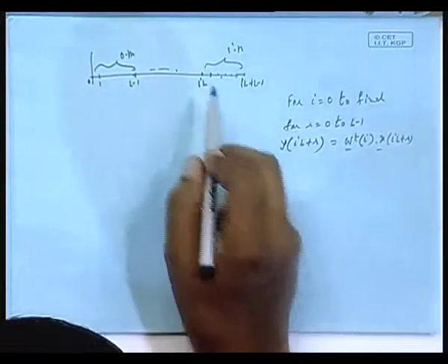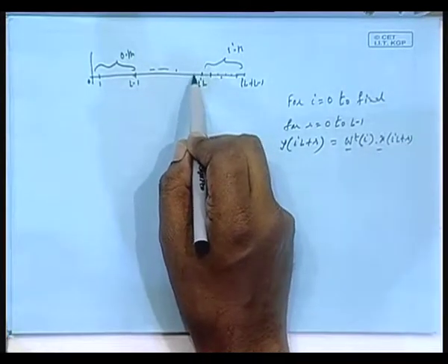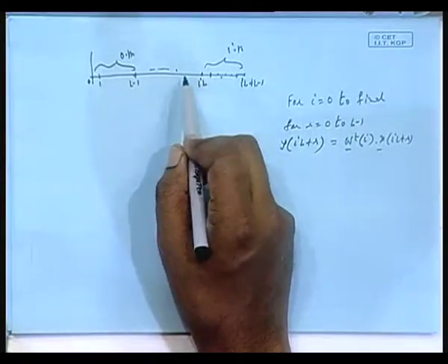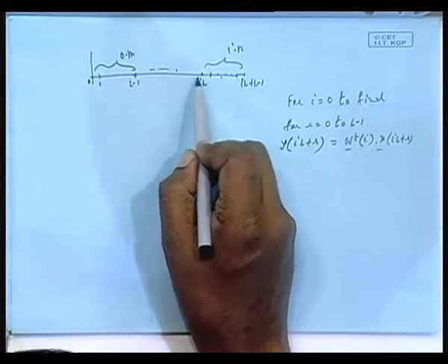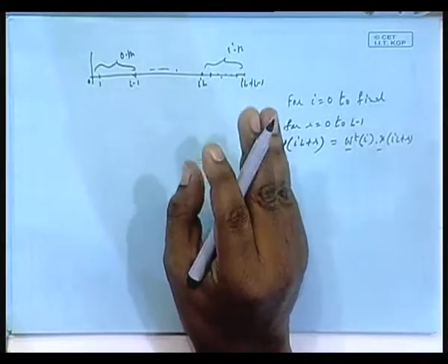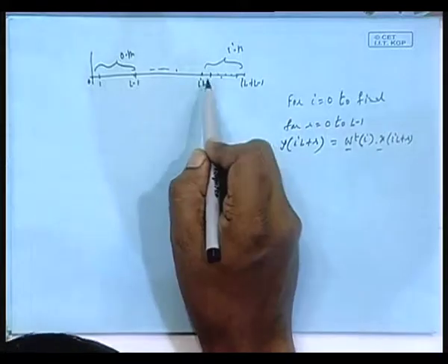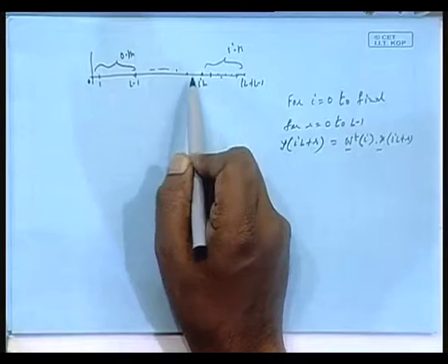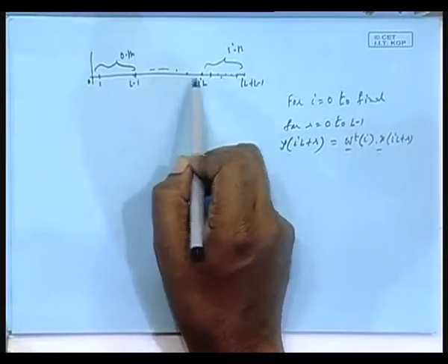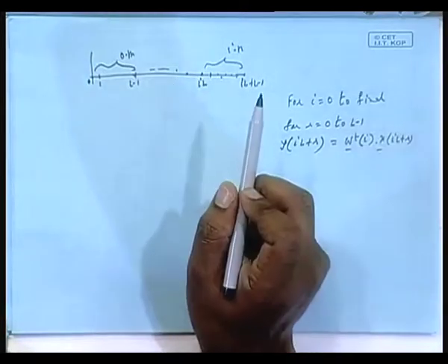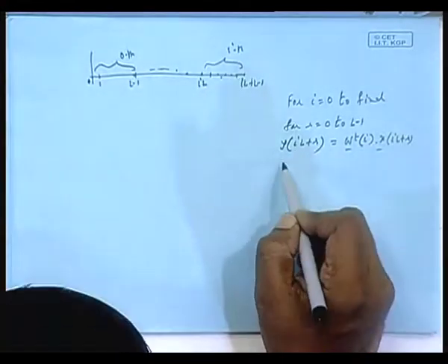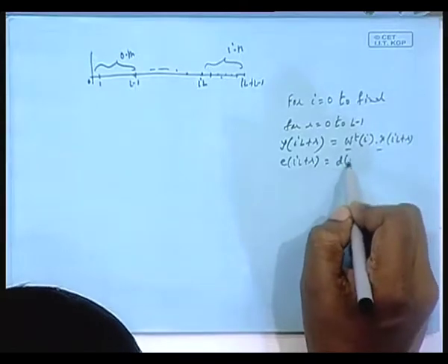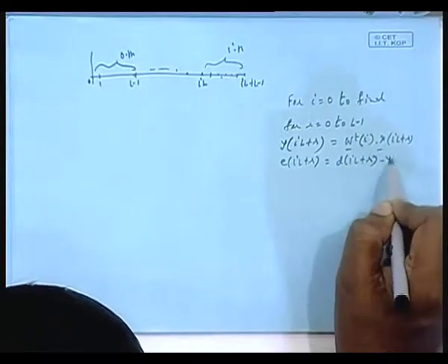And remember, when R equal to 0, you have data not only from here, but from the last N minus 1 data of the previous block, where capital N is the filter length. So you have to have those data stored also. Then here also progressively less, but you need to have a maximum of N minus 1 data of the previous block stored. So this is your output. Then d at IL plus R was your desired response. This is fine.